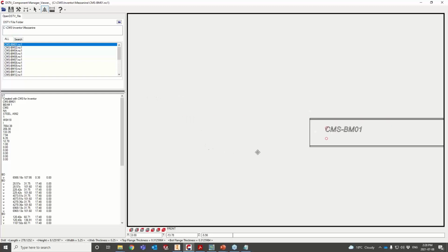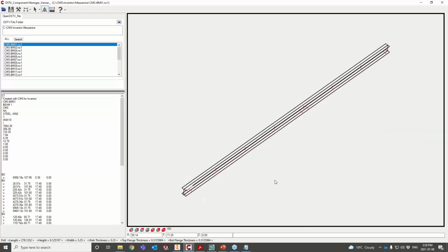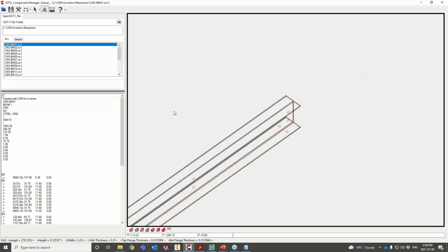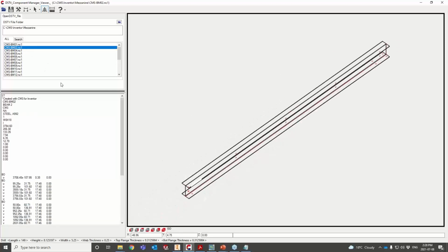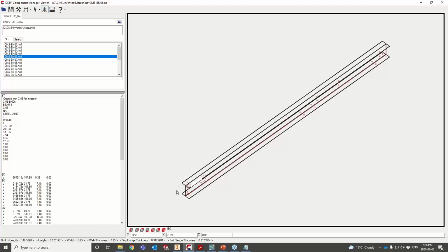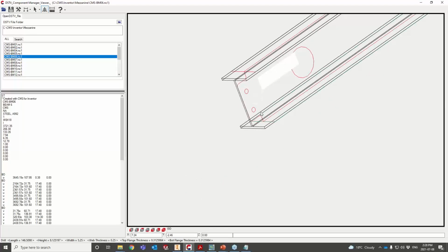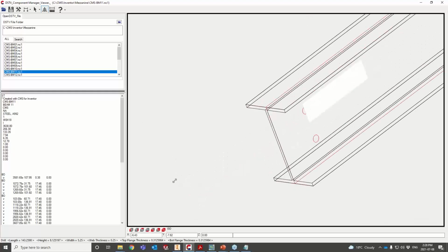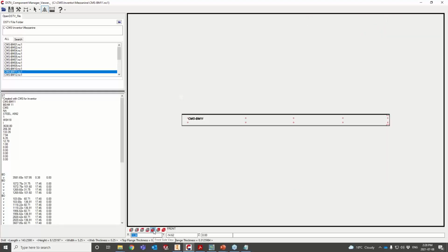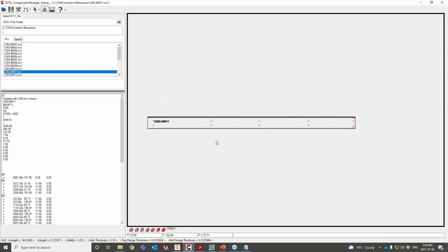As you see, that's my first beam here. You can always zoom in, zoom out. You'll see, verify the NC1s. It was able to grab all the details. As you see, it was able to cope an opening. So all the details came out correct. If you go to the front web view, as you see, those are the stampings of the part number. So everything was batch processed.